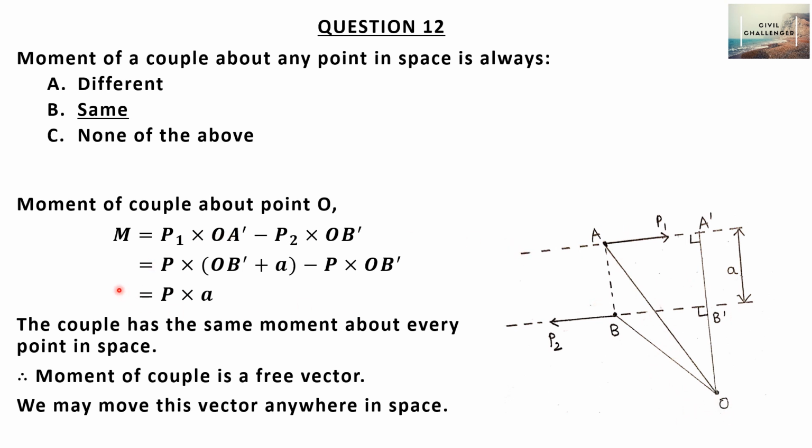Okay, if we calculate that, first we need to consider the moment of force P1, which will be equal to force P1 into OA dash. Okay, the magnitude of force into the perpendicular distance between the point and the line of action of force. Okay, and similarly